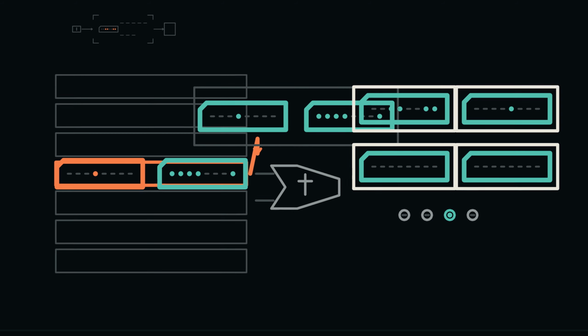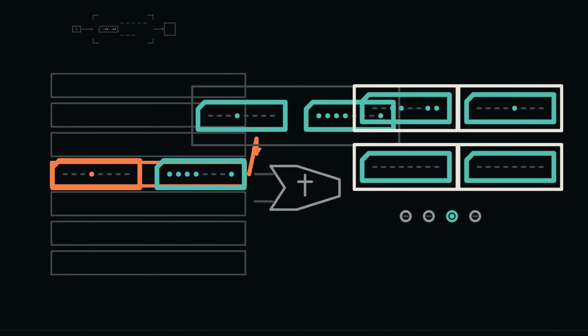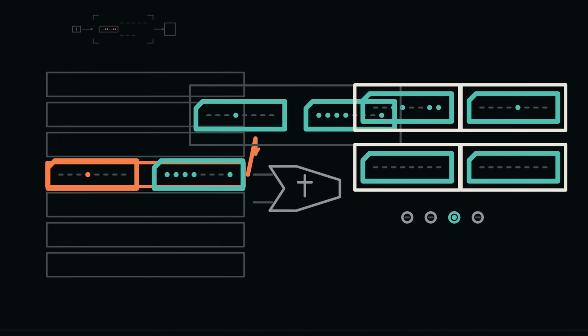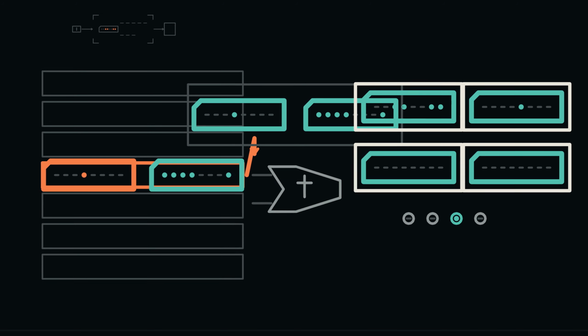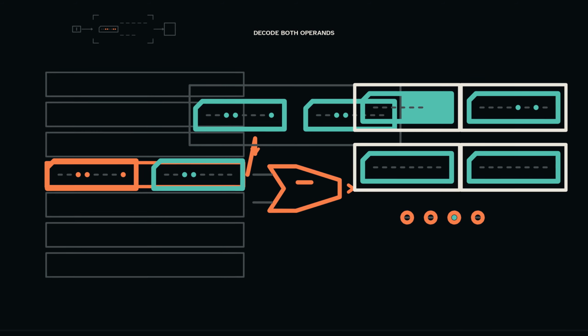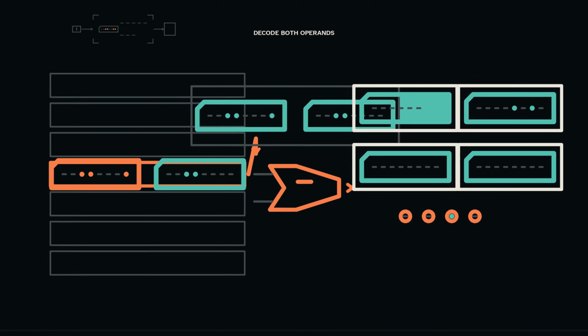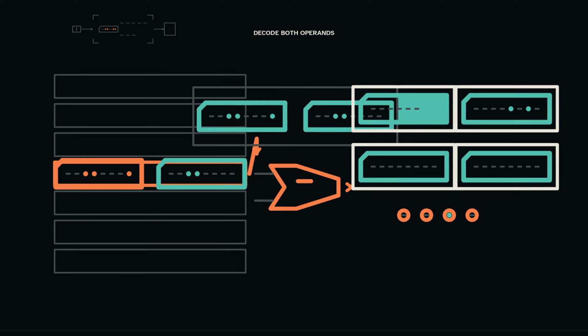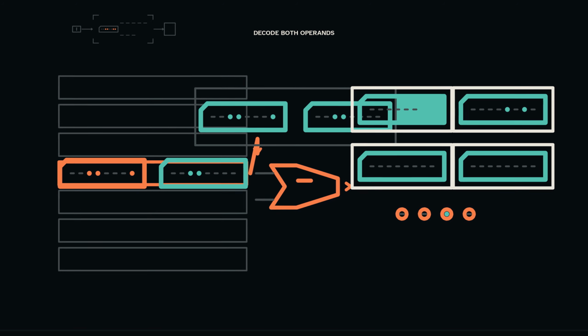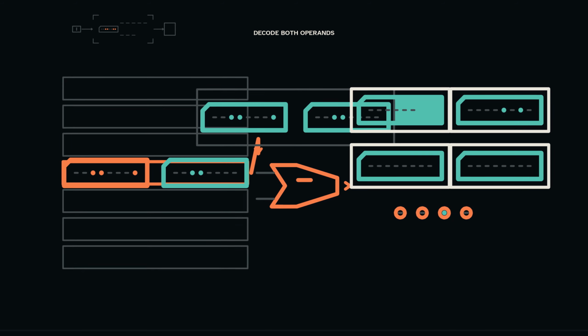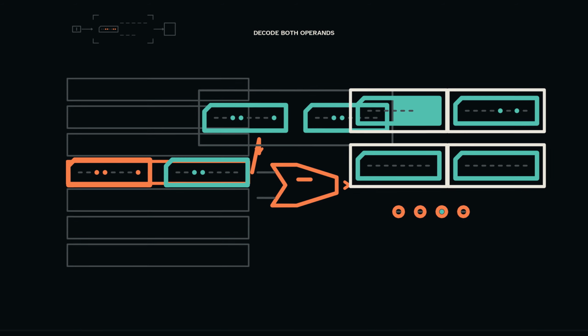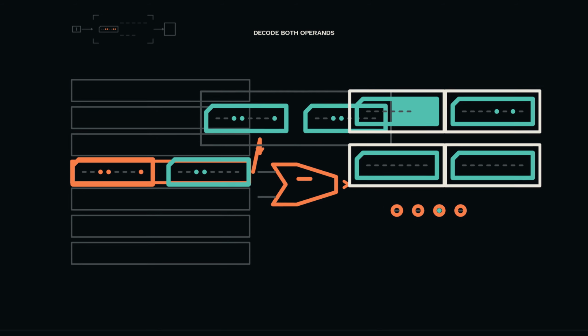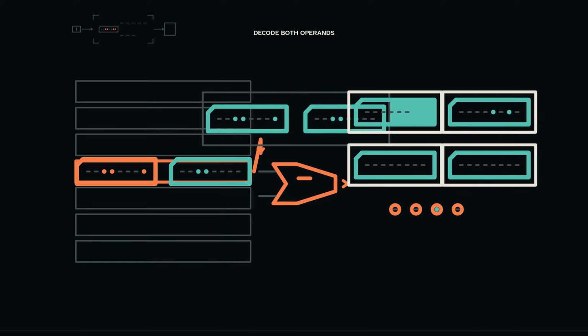The later plus and 5 inputs have not happened yet. Neither is part of this signal, this report, or this queue entry. The consumed byte is hexadecimal 33, the text code for the digit character 3. It is not yet the quantity 3. Digit codes are consecutive, so subtracting the 0 code offset, hexadecimal 30, produces hexadecimal 03. R0 now holds numeric 3.